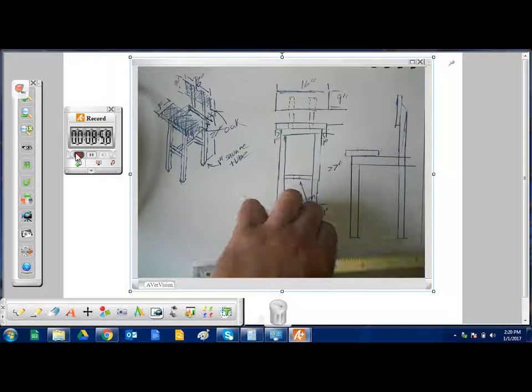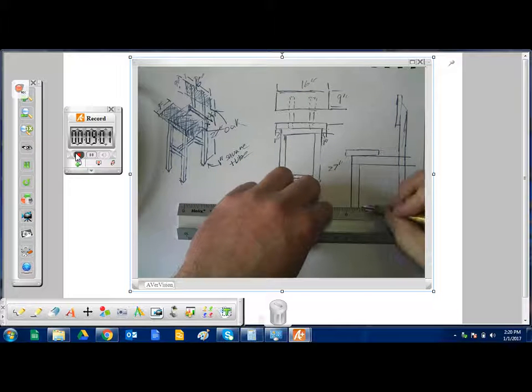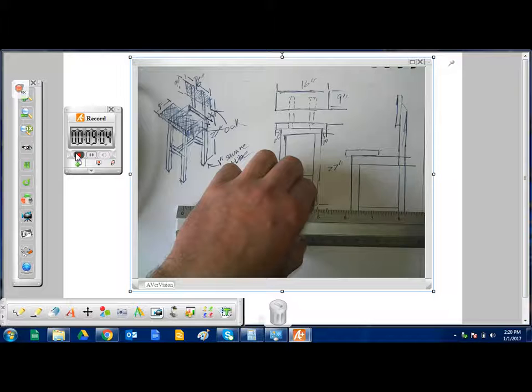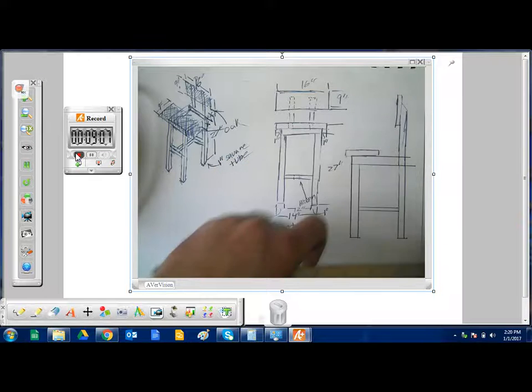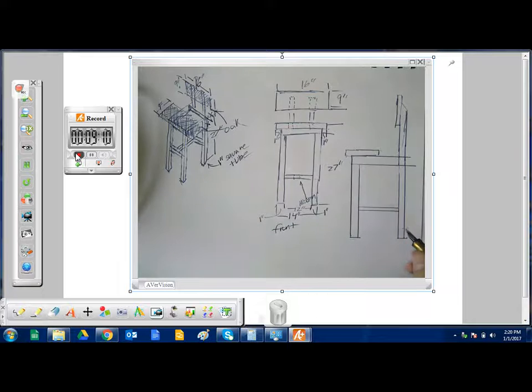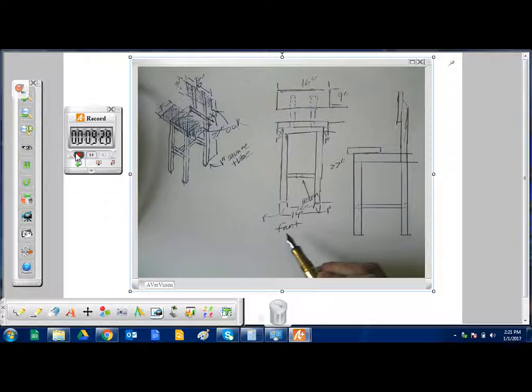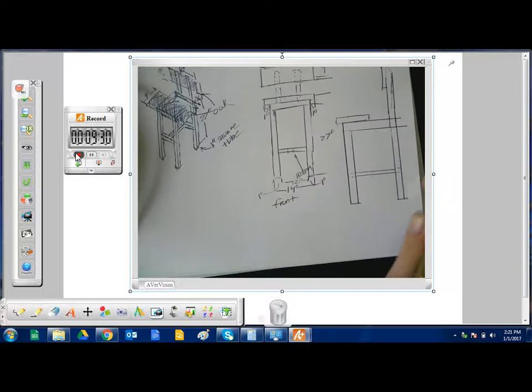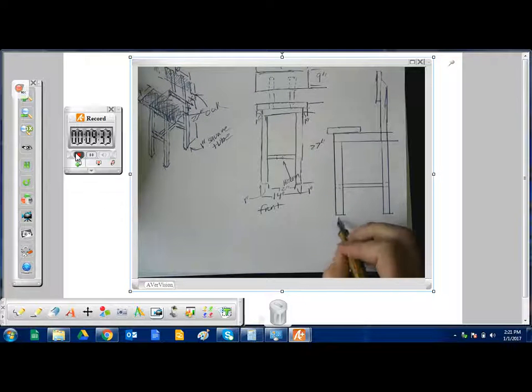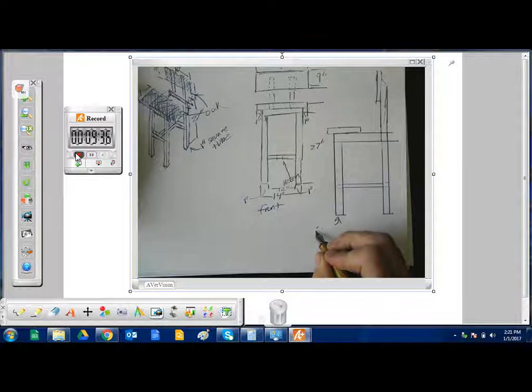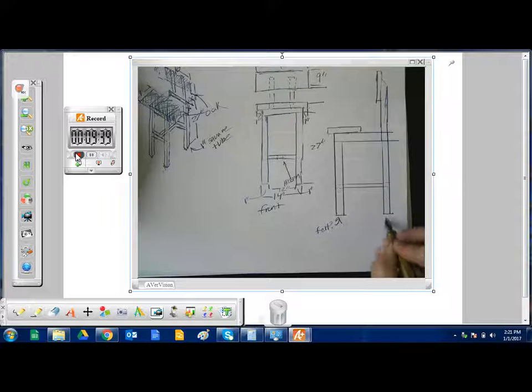And then just put that there. And then I was going to do that cross piece there to keep the whole thing together. I know I'm going to be using 1-inch square tube. I'm going to be welding everything together, so it should be fairly strong. But I'm not going to actually test it at all, because I just know that if I try and weld it and rely on my welds and the 1-inch square tubing to support everything and don't have this cross piece in, this leg is going to go way over here the first time I try and sit on it. So it's not worth trying. We're just going to weld everything together with these cross pieces. It'll work great. And then let's see, felt or plastic thingies.